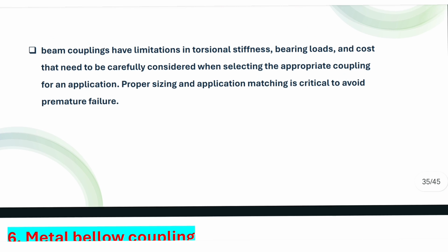Okay. Beam couplings have limitations in torsional stiffness, bearing loads, and cost, which need to be carefully considered when selecting the appropriate coupling for the application. Proper sizing and application matching is critical to avoid premature failure.